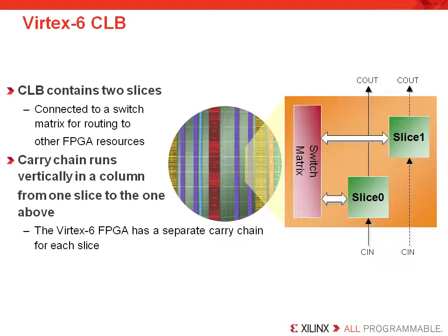The SLICE resources are the most essential and fundamental to an FPGA design. They include LUTs and registers. LUTs are built to create your combinatorial logic resources. Each has an associated register with it. The LUTs and registers are grouped into slices, which also have other dedicated resources. Besides LUTs and registers, slices also have carry logic resources, which are designed to implement arithmetic logic functions with high-speed performance due to the dedicated carry chain, which runs vertically in columns from one slice to the next.